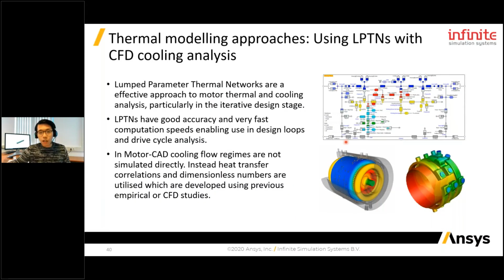And of course, in Motor CAD, we have this lumped parameter thermal network to quickly run the simulation. But if you want to calibrate with a higher fidelity CFD solver, that's also possible. So that's also a typical workflow that people use Motor CAD with.